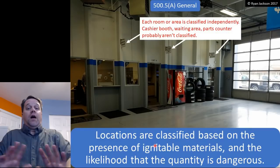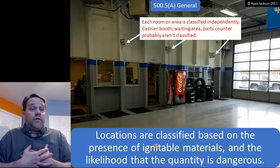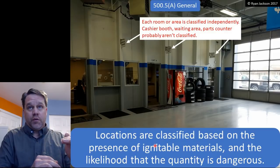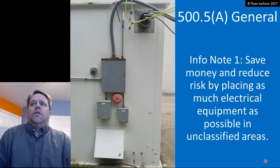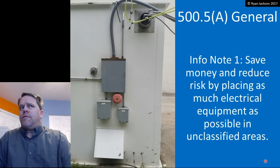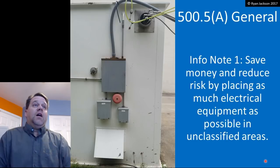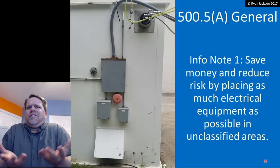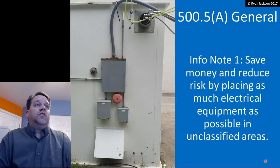Now look, I'm not telling you how to classify the area. I'm just telling you, in my world, I'm not going to classify an area based on the presence of a bottle of fingernail polish remover. I'm just not. There's an informational note here that says you should save money and reduce risk by placing as much electrical equipment as possible in an unclassified area. Yeah, this is not something that the code would normally tell you to do. The code doesn't really tell you about saving money, but it does concern itself with reducing risk.